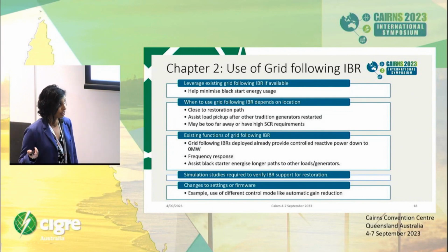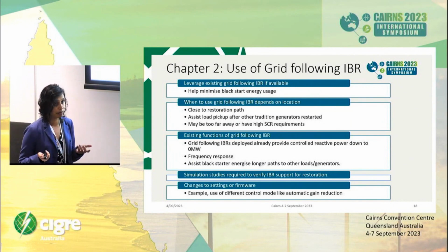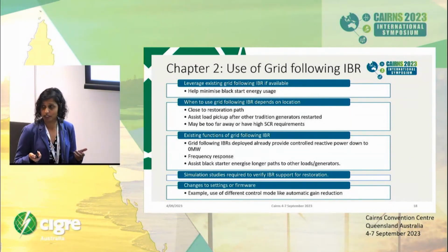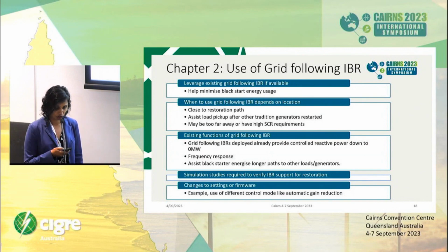Simulation studies are obviously required to verify the functionality of these grid following plants, and dynamic studies are also important to ensure that they can ride through transients to restoration, and Lalan will cover that in more detail. The other thing to consider is that just because a grid following plant is installed with certain features doesn't mean it can't be modified to be used during restoration. For example, firmware settings changes could be implemented, such as automatic gain reduction, which has been used in SVCs.